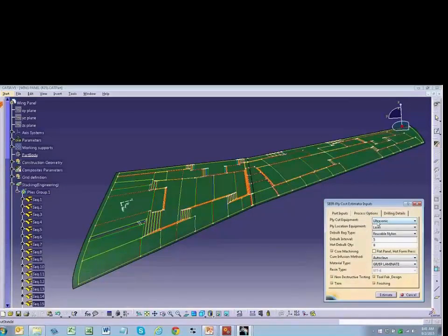So we're using Apply Cut equipment, ultrasonic cutting, laser location equipment. We're using a reusable nylon bag, estimated debulk interval of 5, and we're going to use the autoclave infusion method with non-destructive testing included, tool fabrication and design, trim and finishing.